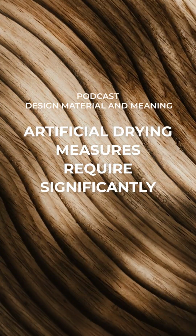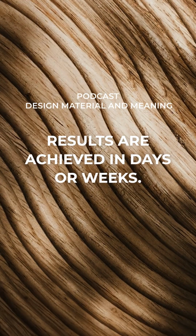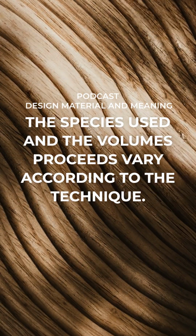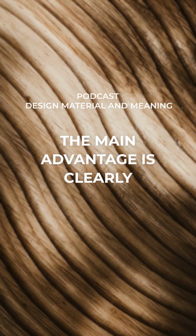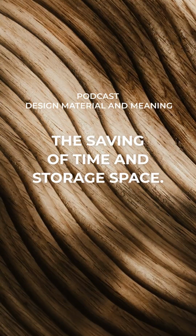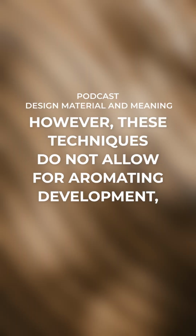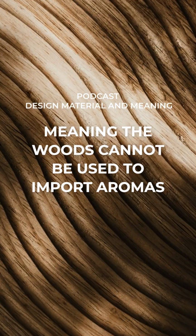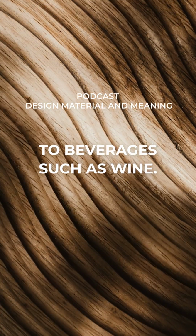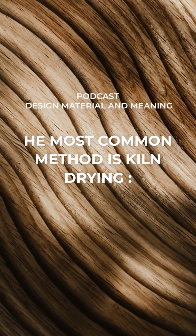Artificial drying methods require significantly higher financial, technical, and energy resources. Results are achieved in days or weeks. The species used and the volume processed vary according to the technique. The main advantage is clearly the saving of time and storage space. However, these techniques do not allow for aromatic development, meaning the woods cannot be used to impart aromas to beverages such as wine. The most common method is kiln drying.